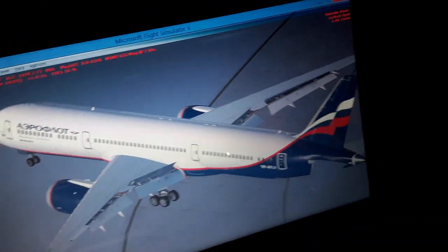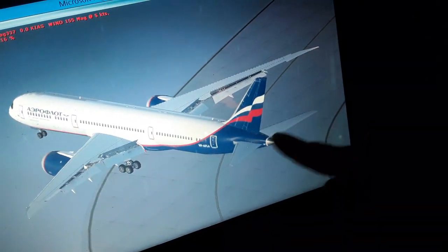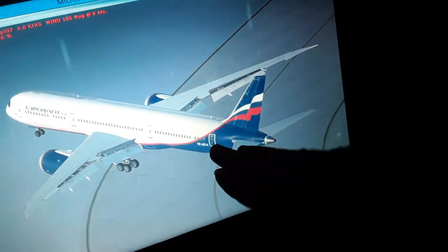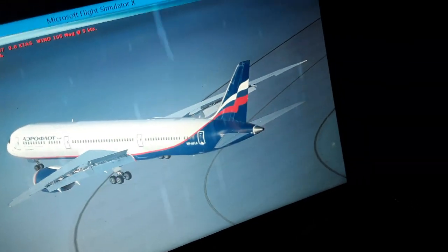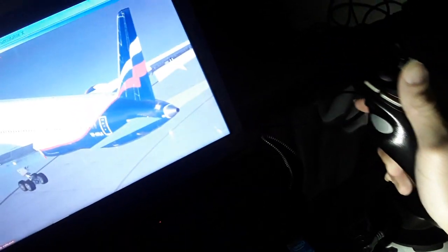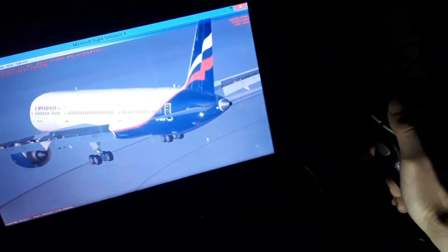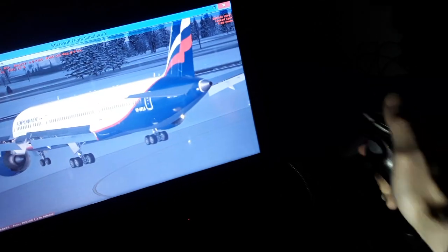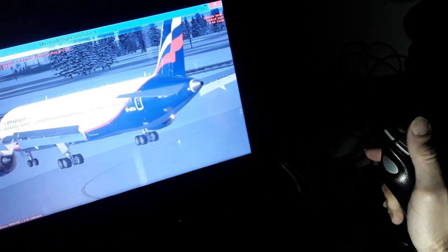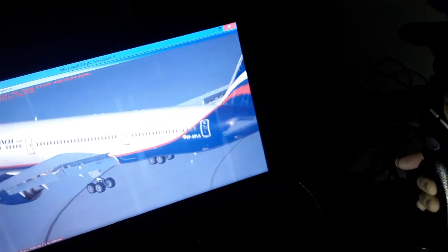So you can see this is the horizontal trim. This is the horizontal tail plane. The horizontal tail you need to trim up or trim down during the flight. You can also use the elevator on the horizontal tail, which is only a small section, using the side stick or the yoke of the aircraft like this. Descend and climb, as you can see. So you can climb like this and you can descend like this. Also use the rudder to make turns, and bank rolls using the ailerons and the spoilers.